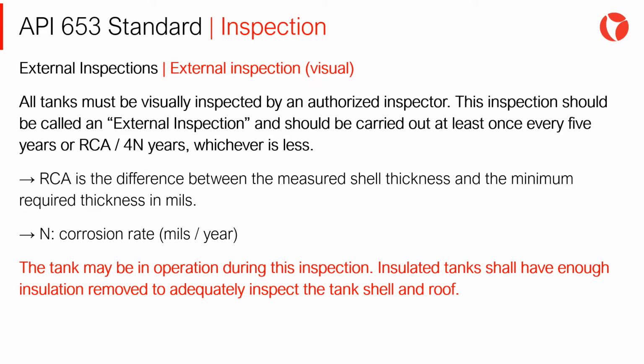The tank may be in operation during this inspection. Insulated tanks shall have enough insulation removed to adequately inspect the tank shell and roof.